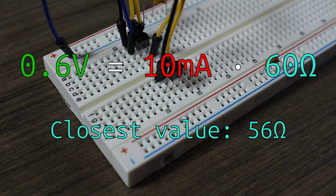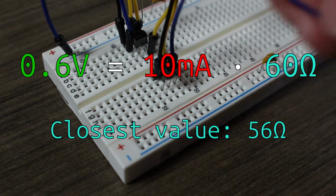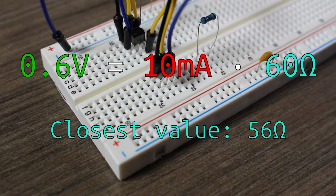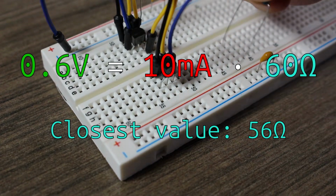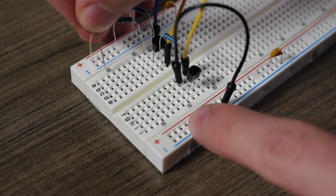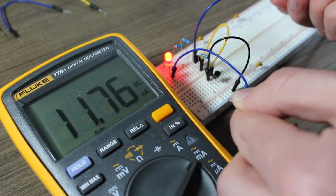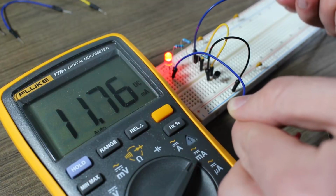Let's say that we want to drive an LED at 10 milliamps. So we can use Ohm's law to solve for resistance. Using these values, we can calculate a resistor value of 60 ohms. Now, I don't have a 60 ohm resistor, so I chose a close value of 56 ohms. Now, if we place our LED and measure the current, we get a value of 11 milliamps. This is really good, and we can even change the supply voltage and still get that same current flowing through the LED.